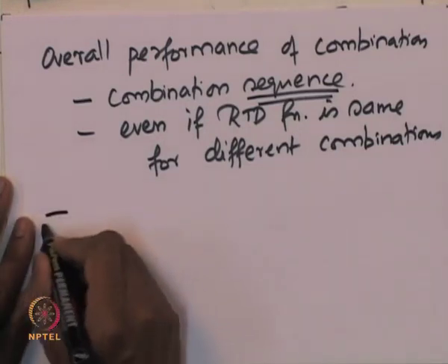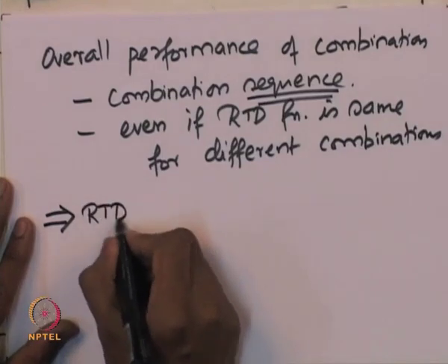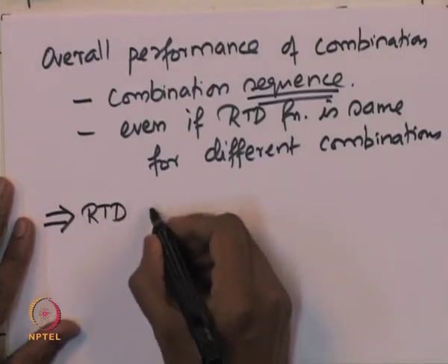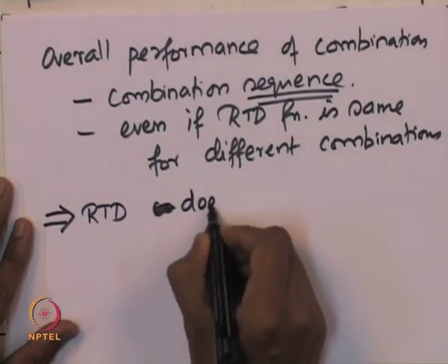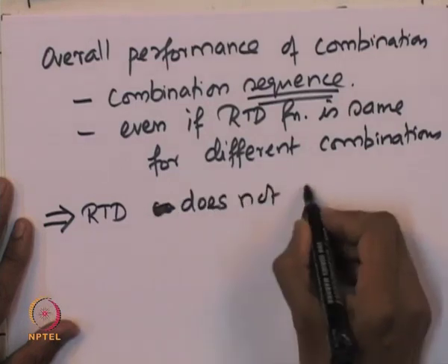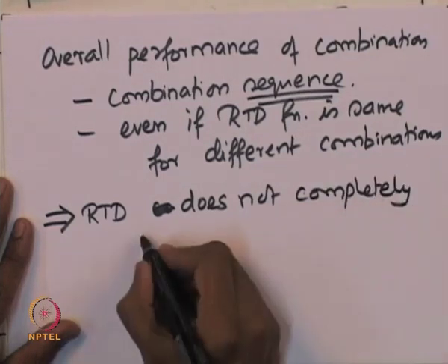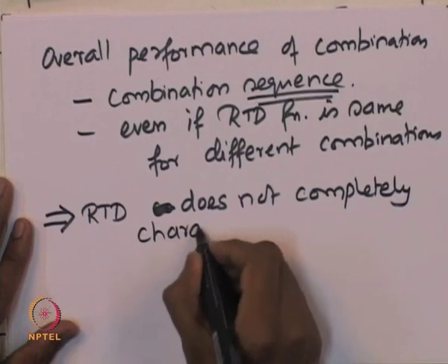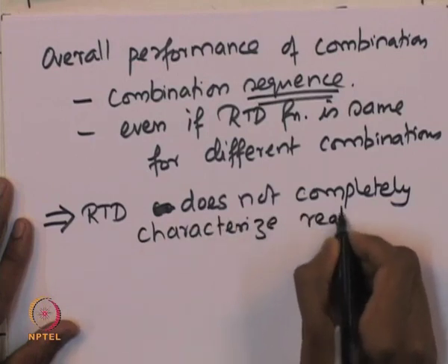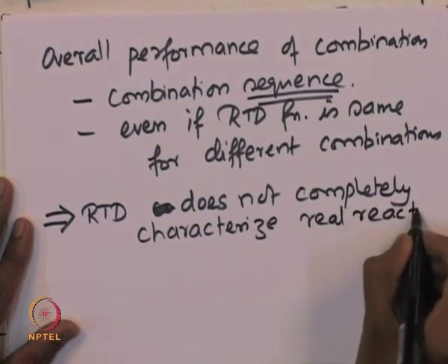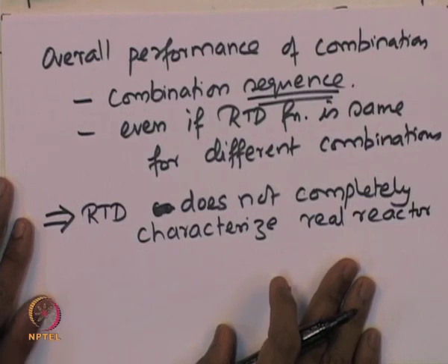So, this clearly shows that the RTD function does not completely characterize the real reactor situation.